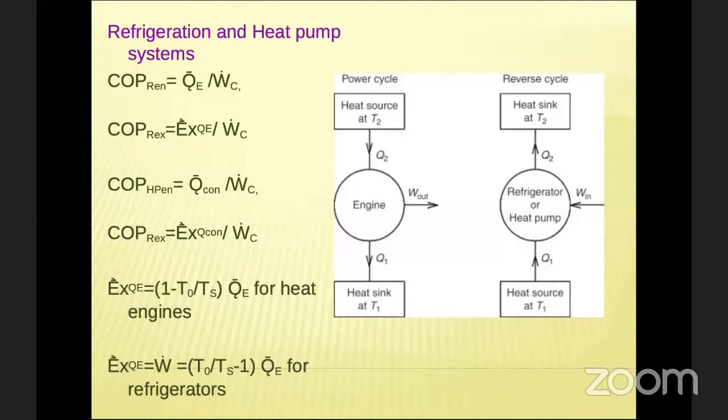Okay, for heat engines. And for a refrigerator it will be reversed, (T naught minus Ts), because in refrigerators it is not the efficiency, it is the coefficient of performance. We are using the power input to achieve the cooling, whereas in engines we are getting the power output.